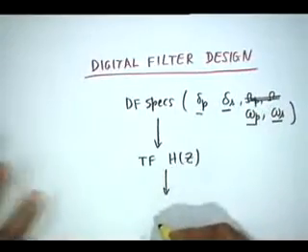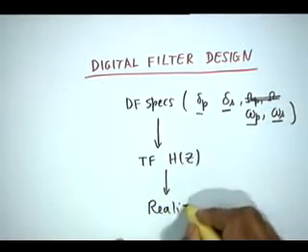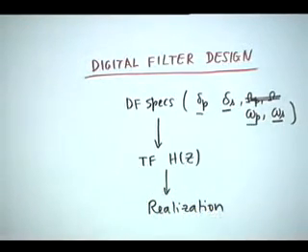Okay? So, the transfer function has to be found, and then once you obtain an H of z, then with the knowledge that you have already acquired, you realize, then you go either to software, write a program with a dedicated PC, or use a programmable chip and program it, or make ab initio hardware realization. If it is very simple or very complicated, it is either extreme, then you design your own chip and fabricate it. If it is in between, then you try to use one of the TI or AD or some other chip, AT&T.